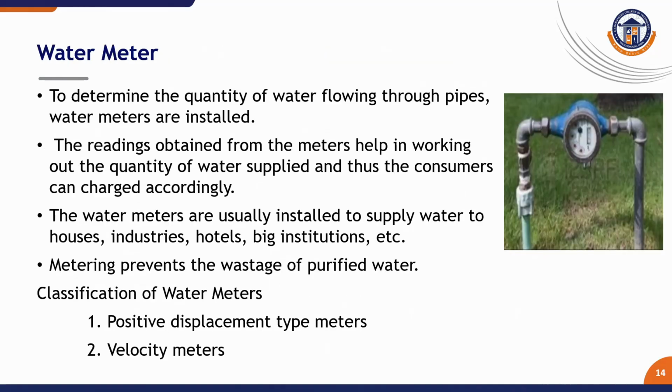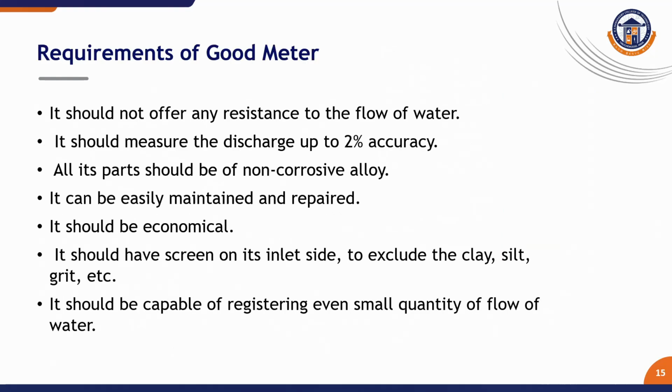Water meters are not valves but are vital appurtenances in a distribution system. They measure the volume of water passing through a pipeline. They are applied in the domestic water supply or industrial uses or for monitoring the billing system. There are two major types of water meters. One is positive displacement meters suitable for low flow rates, and the other is velocity meters, used where water demand is high.